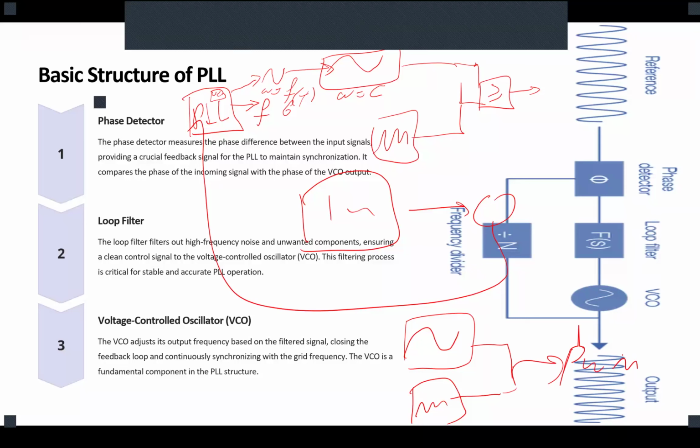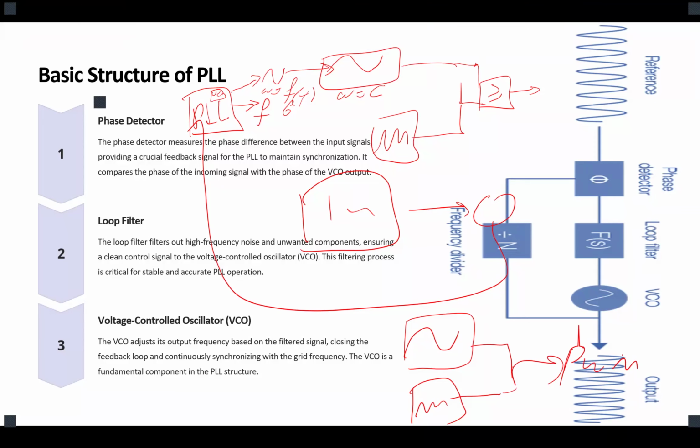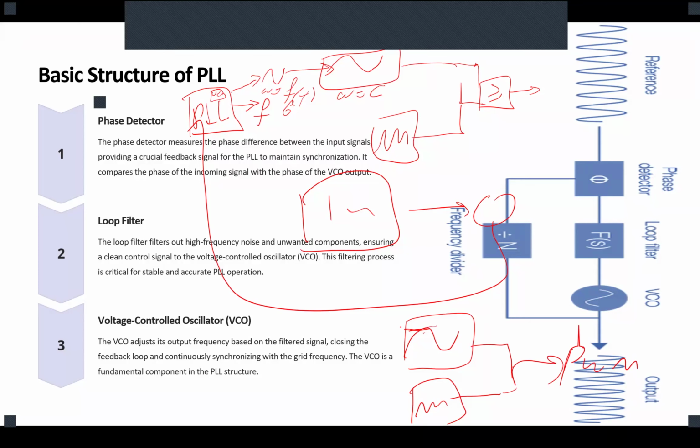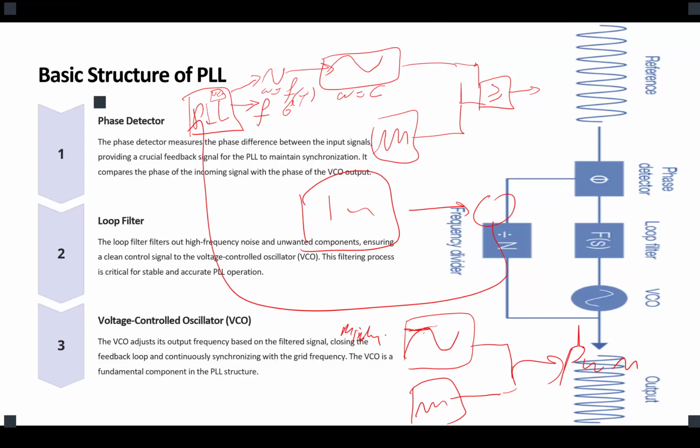Based on the amplitude of our voltage, we could control the reactive power interaction. So who decides the amplitude of our reference, which is the modulation index? You remember that? By changing the modulation index, we could change the level of voltage at the output of the inverter, meaning we could either inject or consume reactive power.